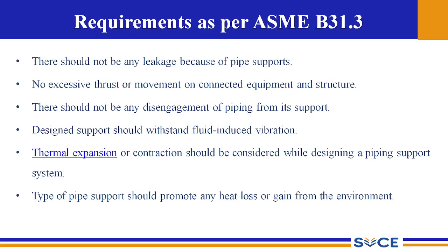So the support, instead of doing its original function, will accelerate the descent of the pipeline along a slope. This kind of scenario should be avoided, and after installing the support, there should not be any disengagement of the piping from its support.